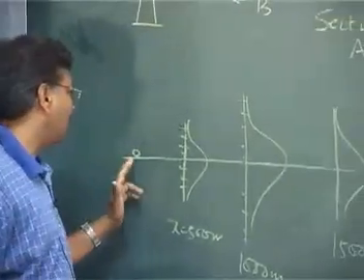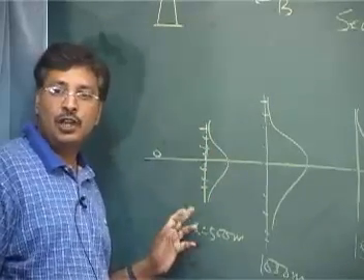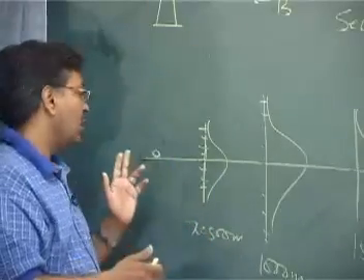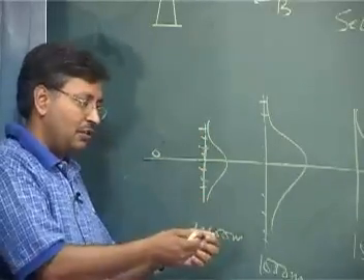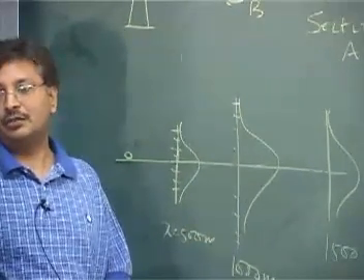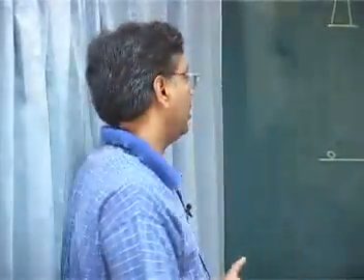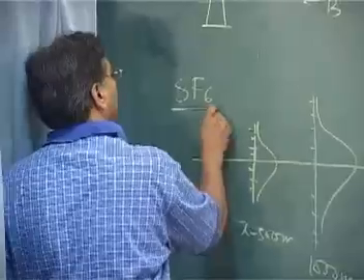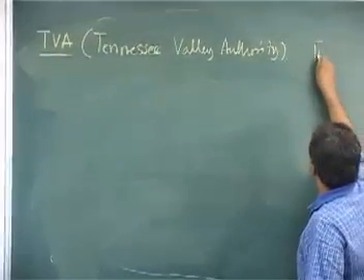So what they did, they ran this experiment by releasing some tracer. Because if you are doing it with sulfur dioxide, it will always be in this area from some other source, and results will be a mixture of sulfur dioxide from various sources. So they release some tracer that is not there in the atmosphere, so they can accurately measure. They go into the fields with a small handy gas chromatograph or some such instrument, and they measure at different places of y at the same time. Suppose 10 people stand with their monitors, and then they release the tracer. The normal tracer that we use in air pollution study is SF6. The person involved was the same person who talked about stability, that was Turner and his team.